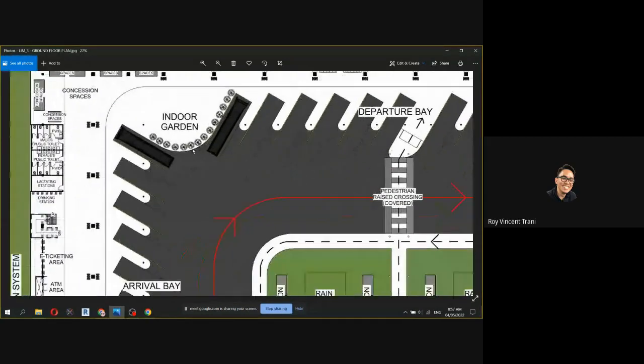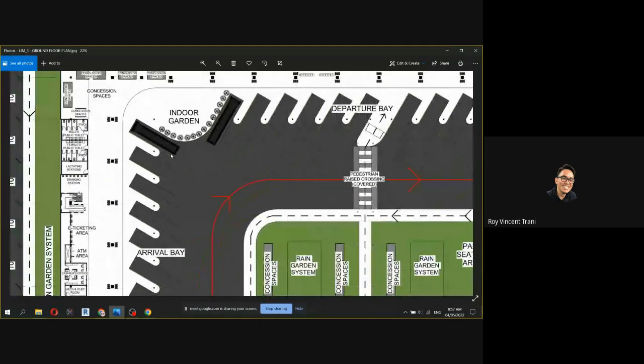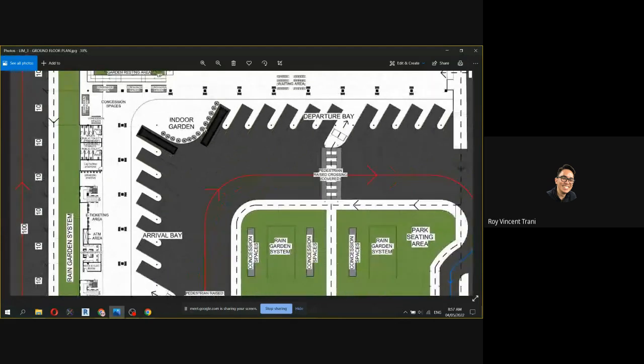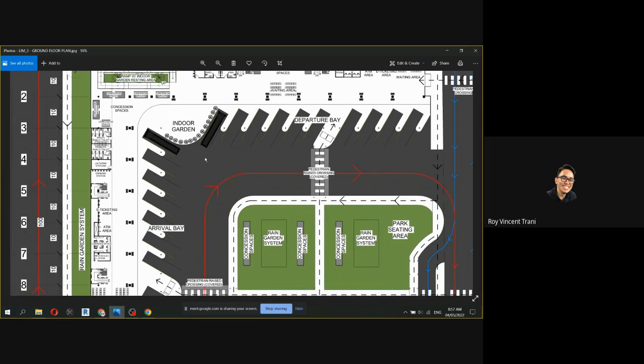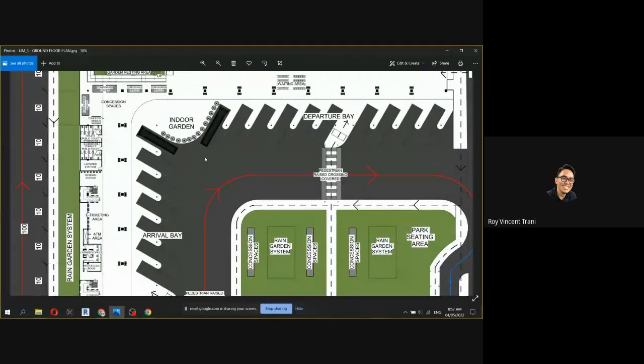Okay, so they take turns at the exit. I'm just asking what those block rectangles were. Maybe for that corner, you can remove either the left side or the right side. I think if you measure it now, they have enough backing space. They would need about 3 meters backing space, and if it doesn't intersect within 3 meters, it's okay.